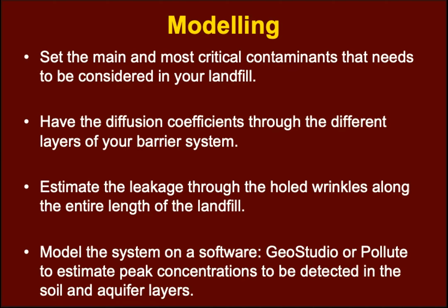And after that, you would use software such as GeoStudio or Pollute to model your full design, which includes the barrier system and the landfill. And these software will be able to give you the concentrations in the soil and aquifer over time. So once you have the peak concentrations, you need to compare those concentrations with the maximum allowable concentrations in drinking waters or soils for the specific contaminant you are considering.